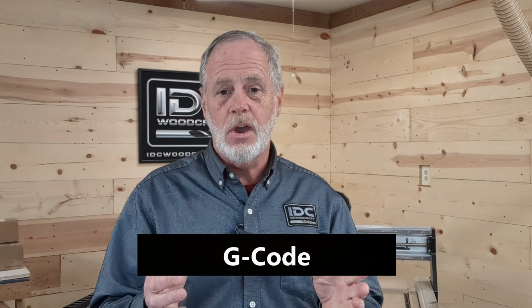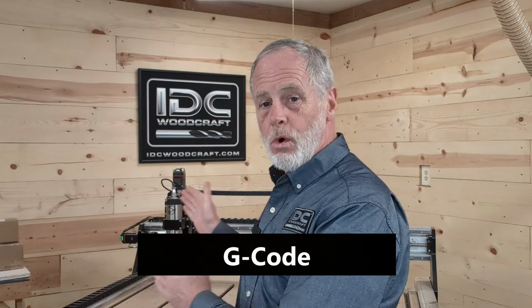And it's the last step that you need to do before you can actually get that project out on your CNC router. Saving toolpaths is basically turning your design and all of the router bit toolpaths that you created into something called G-code. G-code is the language that your CNC router understands that tells it what to do. When you're going to create these files, you actually are done with the Vectric software. Then you have to take those files and plug it into your CNC router control software, and that's how you can run the machine to make it move around.